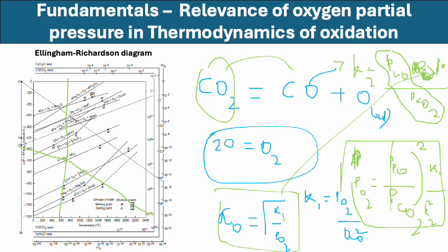This reaction is also quite important in the steel making process, but we are not discussing that context. We are discussing the supercritical carbon dioxide reactors, where carbon dioxide can oxidize the metal alloy component that is used in the power generation apparatus.